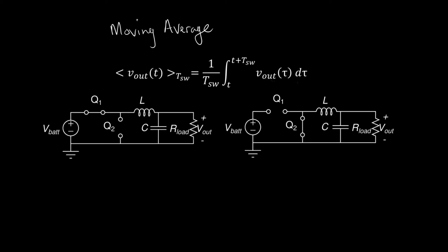Last lecture, I wanted to show you that we can use a transistor as a switching element instead, and when we do, we're able to reduce the losses. We found that the efficiency of a resistive divider was related to the input and output voltages. If we used switches instead of resistors, we were able to avoid that loss associated with the resistive divider.